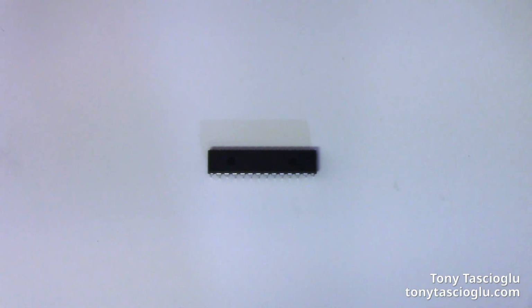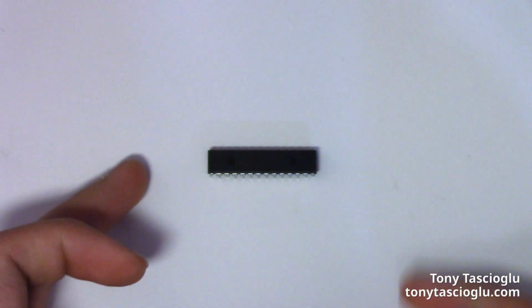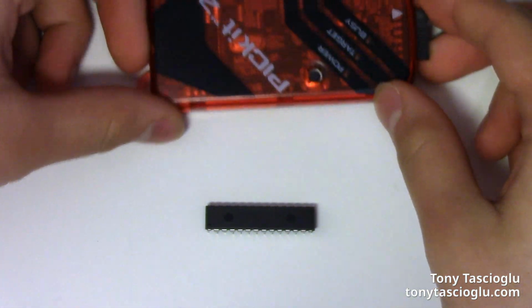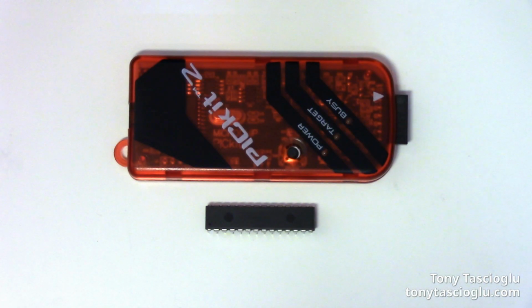Now, a similar thing exists for a lot of things. For example, to use STM32 boards, you need an ST-Link USB adapter. Similarly, for PIC boards, you need a Microchip PIC programmer. So for this, I will be using a PICkit 2. These programmers can be had for cheap, around $10–12 on eBay, depending on when and where you look.